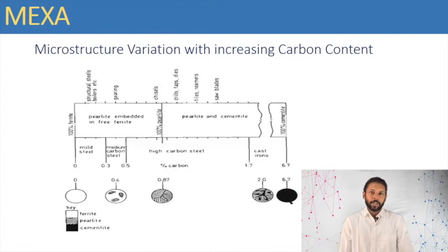Carbon content for cast iron may vary from 2% to 4% approximately. This carbon may be present in either the form of cementite or graphite, depending upon certain factors, one of which is the cooling rate. Grey or malleable cast iron is composed of pearlite and graphite, while cementite gives white cast iron. This is brittle and difficult to machine and hence does not normally encounter much use in marine work.